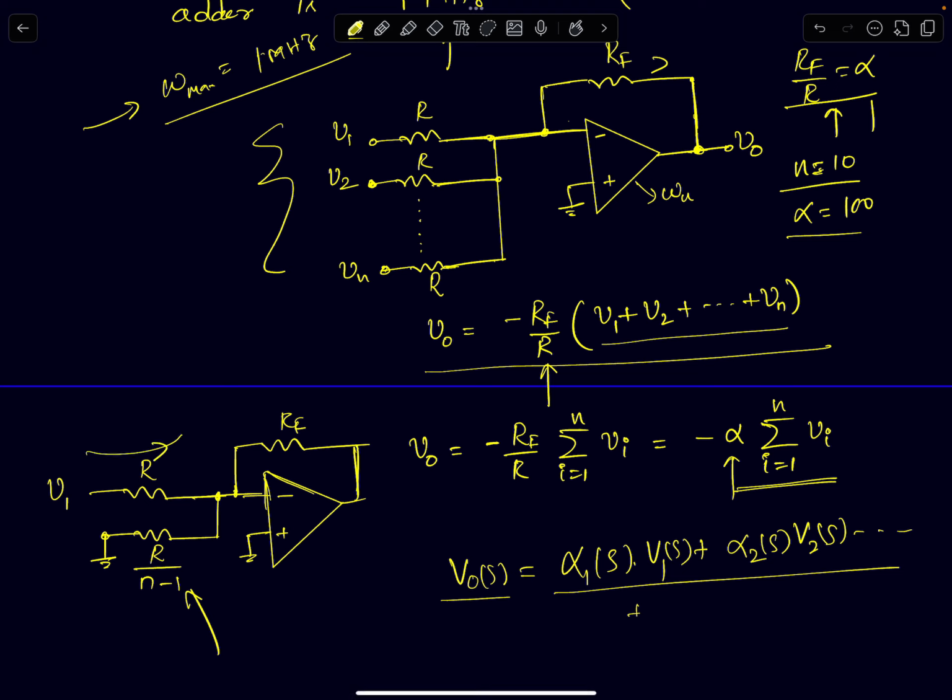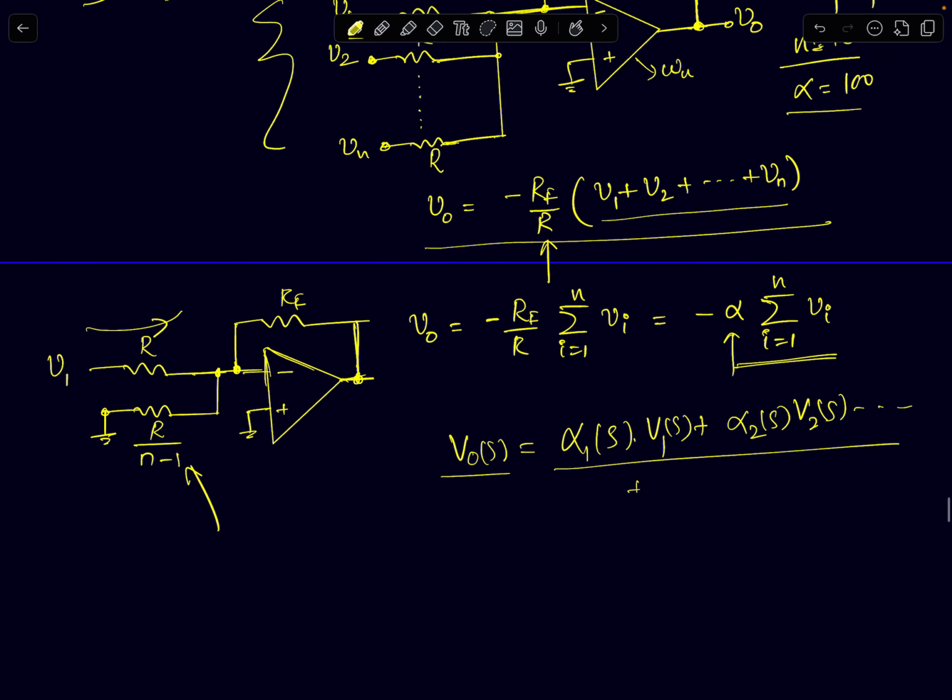Now if you see this circuit, it's slightly different. The feedback factor is finite in the circuit, right? So always remember, anytime you are analyzing the inverting amplifier also, we discussed in the previous example that the closed loop UGB of the system is determined by, I can just assume the input as short and analyze this circuit as it is, and treat whatever signal is fed back, and from that I can compute beta.